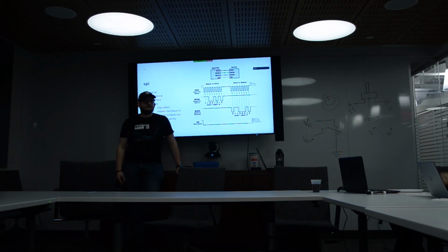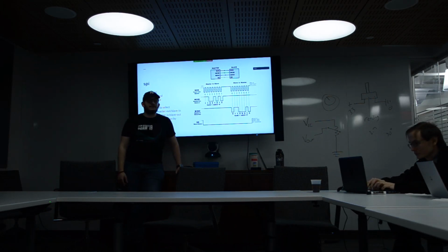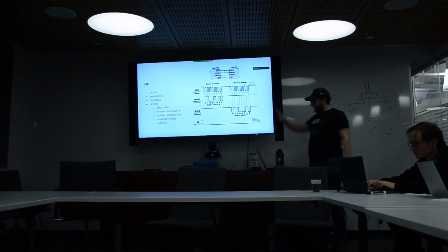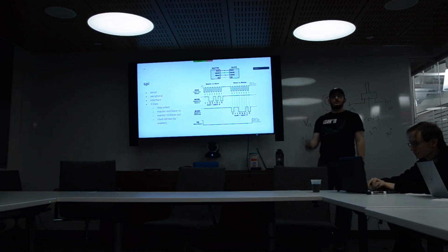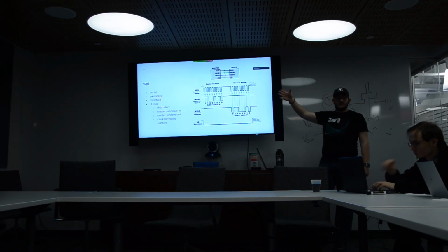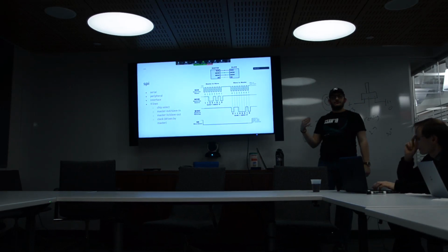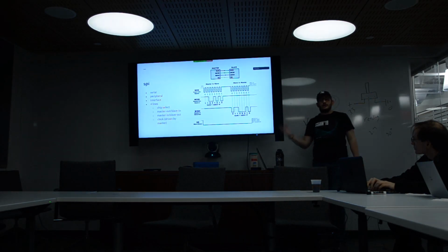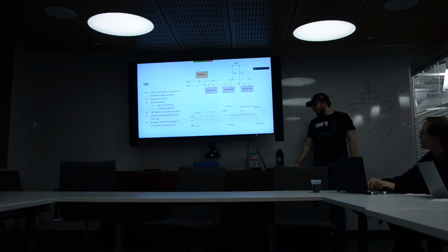Do different sensors require use of different buses? Yes. So SPI is nice because it's really, really simple compared to other things. There's an explicit clock, so you don't have to worry about real timing problems. There's chip select, so you don't have to worry about addressing. This is the simplest serial you can possibly get, which is actually one of the reasons why I showed it first. Then you have I2C, which is the opposite of all of that,